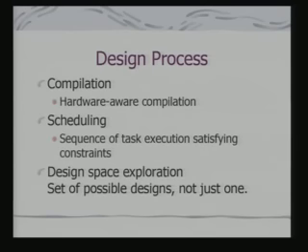There could be other design options. Another design option could be using a 16-bit processor and use maybe a special purpose hardware along with it and meet the functionality as well as the design constraints, timing constraints. Which one to choose? Maybe the 16-bit processor with special purpose hardware finally turns out to be less costly. There may be other issues also. That means both may satisfy the timing requirements and we would like to choose the one which is likely to consume minimum power. So, that is what we refer to as design space exploration.